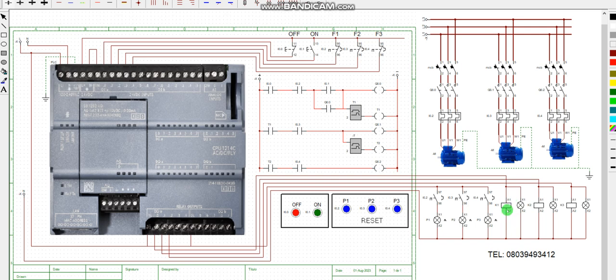For instance, this is my contactor that is representing this module. I just use this indicator lamp to feed from my contactor, instead of sending the whole of this lamp to my logic and also to my output device. So I can take from the coil to make it faster, right? So that is why you see multiple outputs using limited outputs from my controller.